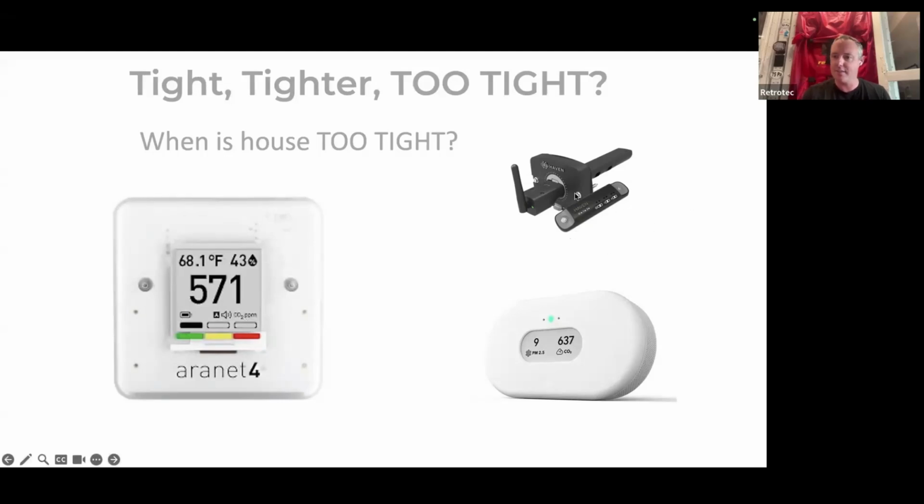I really like the Haven indoor air quality monitor because it's measuring the whole house. You install that into a return duct. It also has a controller that can be wired to open your ventilation whenever your indoor air quality starts to decline. So if your VOCs start to get high, they also have room monitors that read CO2 and communicate with this. So it really just responds to when you need it instead of running it randomly when maybe you don't. Plus, it'll also run your air handler to filter the air if particulate matter gets too high. So it's a demand response approach to ventilation instead of just putting it on a timer. That's a nice way to do it.